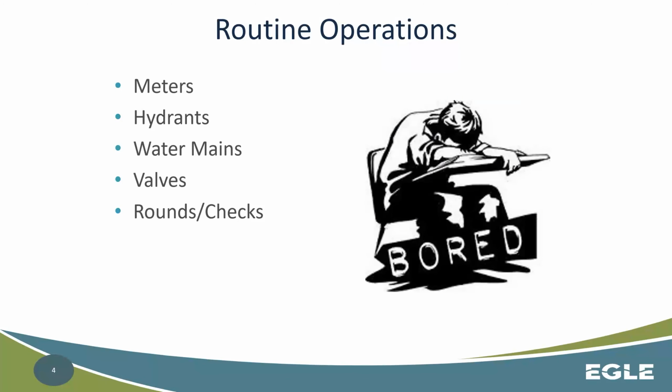So routine operations can be anything but boring, but there are sometimes boring aspects of it, right? Having to check on meters, having to do simple hydrant maintenance, doing water main checks in certain areas to see how flowing and cleaning is going along, doing valve turning programs, or just literally doing rounds around the systems to check that you don't have a fence down, you don't have a vehicle smashed into a building, you don't have a door that's been busted into on a pump station or something along those lines. Just making sure that you've had a routine visit to all the locations within the distribution.